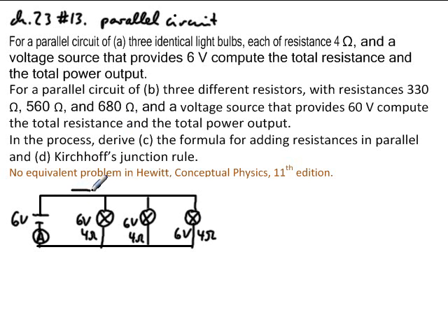As the total current is flowing through here, part of it will go this way, part of it will go this way, part of it will go this way, and all 3 of these here are added up to be the total current, which is what the next thing says. The total current in the circuit equals the sum of the currents in its parallel branches. The sum equals the current in the battery or other voltage source.